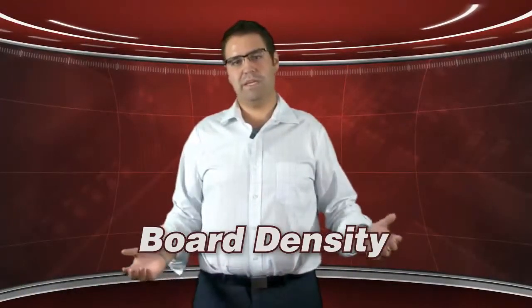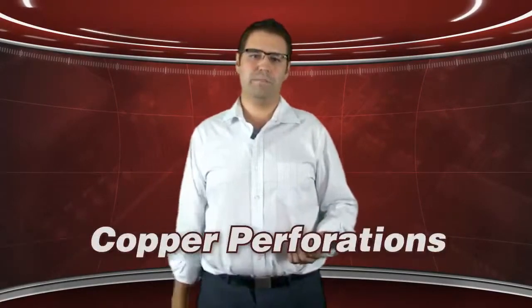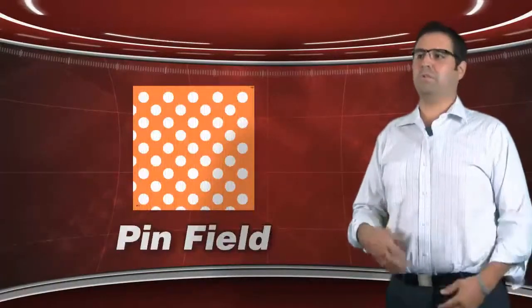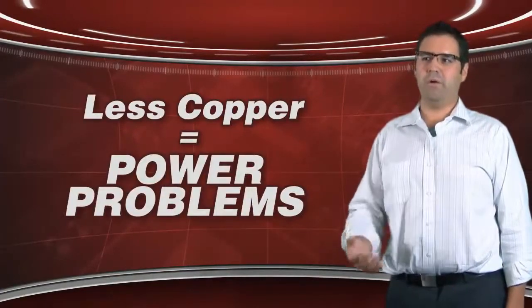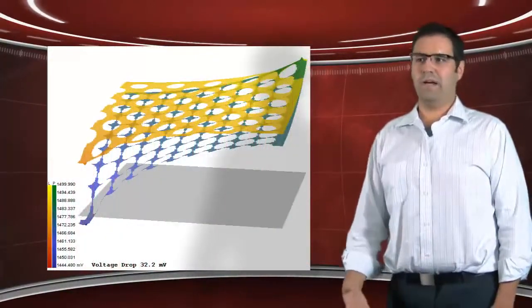As densities begin to increase on the PCB, it creates more perforations in the power planes. So you have all these little perforations in the plane which are reducing the amount of copper, and that's all from the vias that are in the design. So you have less copper that's supplying the power to the IC power pins. So this presents problems specifically with DC drop or IR drop.